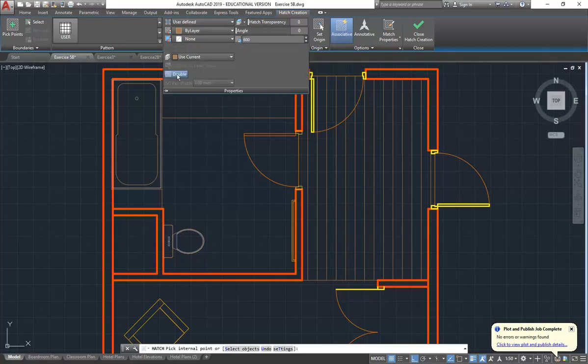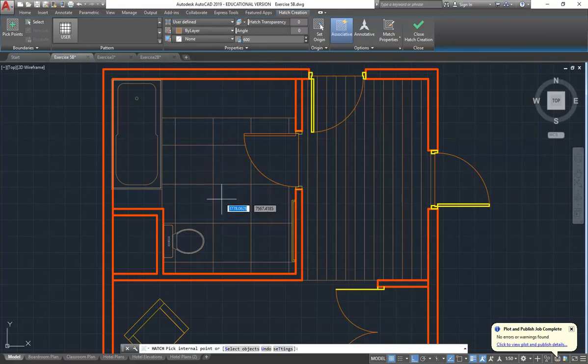I'll click on properties to get that double option. If you haven't got that checked, you just need to turn that on. And you can see as you hover over an area, AutoCAD's really good at finding the area that you need to hatch, unlike, say, Illustrator or lots of other programs where you have to define that shape first. So AutoCAD's tracing around, but you can see I've drawn lines in to enclose that area. You need to have lines that connect the bath and the wall, and also a line at the edge of the door, but that's come as part of the block.